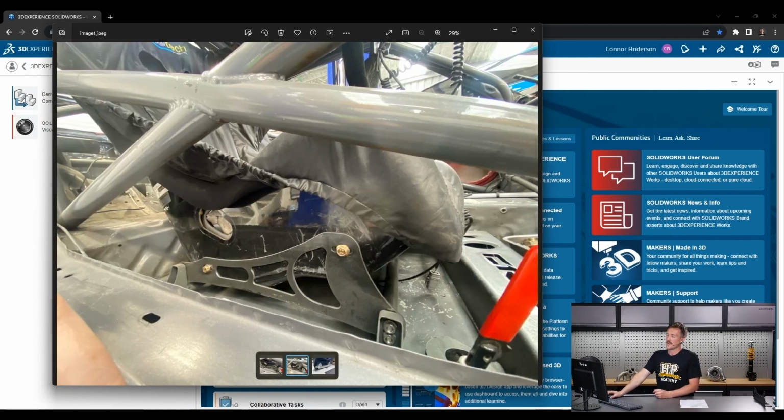And then this is another design here that Brandon actually designed in CAD and fabricated for use in the CRX, which is a bit of a work in progress at the moment. But you can see it has these tubing rails across the chassis for extra strength, and then these brackets mounted to that, which are a really strong design, and then just a single sheet metal piece which mounts the seat there.